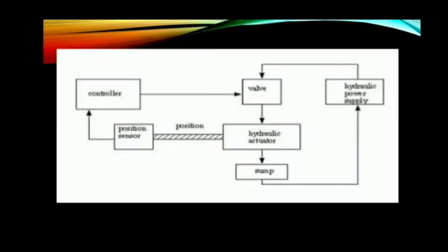Hydraulics is based on Pascal's law, which states that when there is an increase in pressure at any point in a confined fluid, there is an equal increase at every other point in the container. Pressure applied to a confined fluid at any point is transmitted undiminished and equally throughout the fluid in all directions and acts upon every part of the confining vessel at right angles to its interior surfaces. In simple words, intensity of pressure in fluid is equal in all directions.